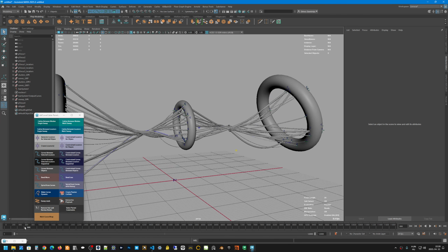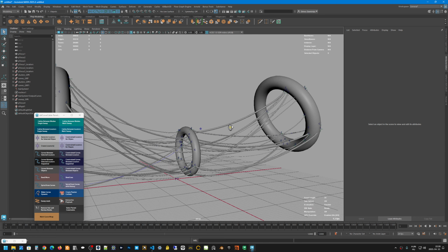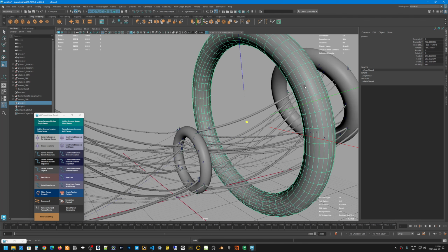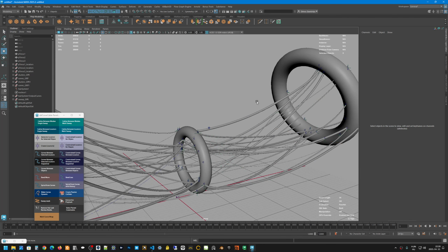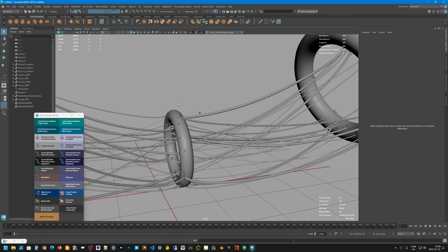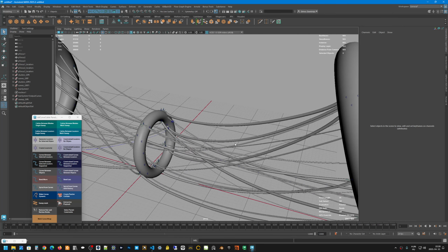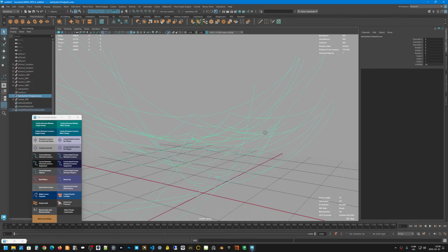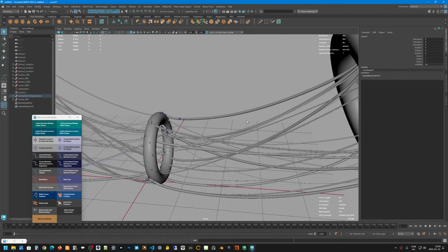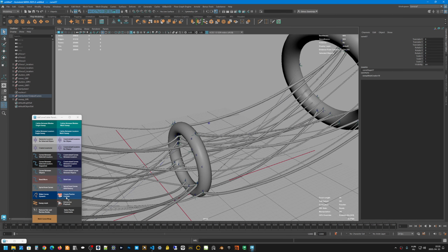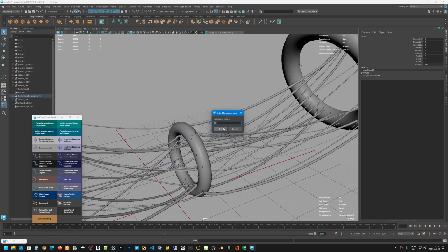Now if you go back to the first frame, of course the animation is not stored. We did not do that, so you will lose those things. But I can show you another thing. For example, with this curve, I want to generate a spiral around this one. So I select the curve and I press spiral from curves with history, number of loops. There is a trick here.